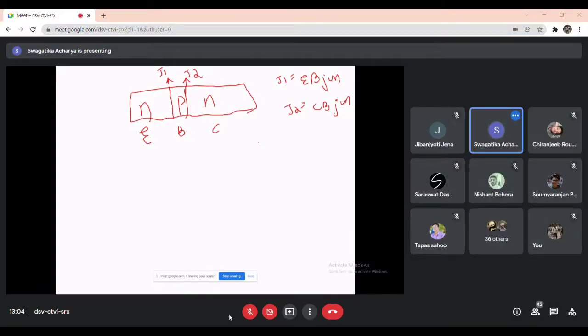The base emitter junction is in forward biasing mode, so the depletion layer will be small, allowing low resistance. It provides a low resistance path for the charge carriers to flow from the emitter to the base.